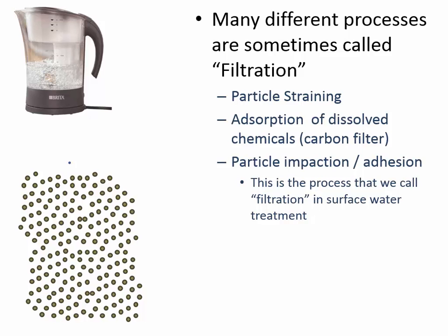Just for whatever reason, maybe it never had an impaction, or maybe it got broken apart because we stirred it too quickly. It could have been sheared apart. But what we know about this particle is it's still destabilized. It still has all of the positive charge surrounding it from coagulation. Remember, we chose alum and iron because the particles had a negative charge on the outside of them, and alum and iron both have a +3.